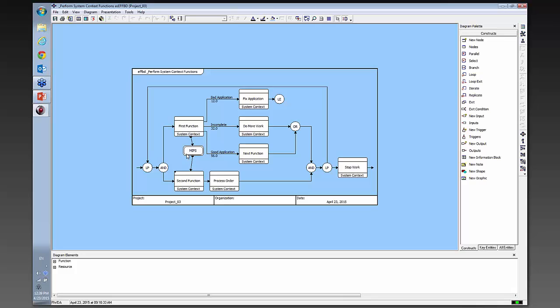I've also set some relationship attributes. First function produces MIPS, and there's an attribute on that produces, and I currently have that set to 2. The consumes relationship also has an attribute, and I currently have that set to 4. Let's see this in simulation. And it failed. Take a look at my blocking events. This is precisely what I wanted to see happen, and I'll admit to having rigged it to work this way for our demonstration. And we'll start looking at it from the bottom.